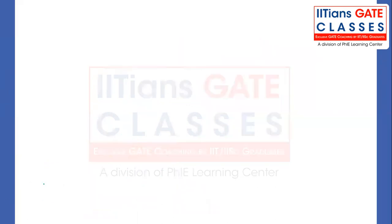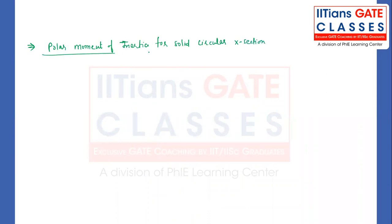Apart from it, the polar moment of inertia is a very, very important thing. For a solid circular cross section, J can be written as pi d power 4 divided by 32.